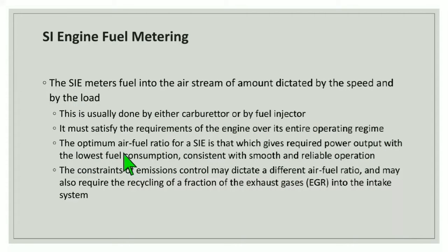The optimum air-fuel ratio for an SI engine is that which gives the required power output with the lowest fuel consumption, consistent with smooth and reliable operation. The constraints of emissions control may dictate a different air-fuel ratio and may also require the recycling of a fraction of the exhaust gases into the intake system.